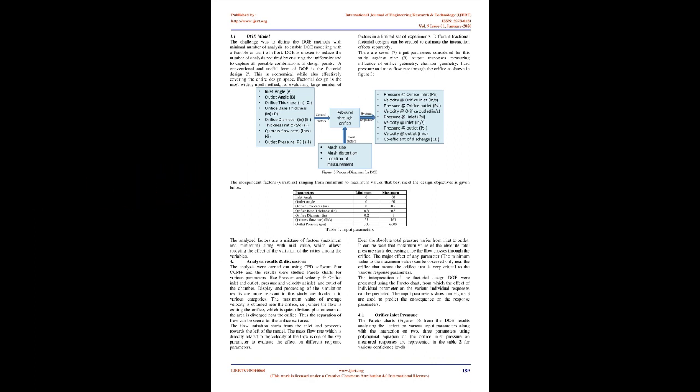Figure 2 illustrates a general structure similar to the undercarriage flow structure. The element size is finalized after various iterations of sensitivity study, such that the flow field could be captured as accurately as possible. Also, 2 volumetric controls are created near the orifice to capture the detailed flow information.